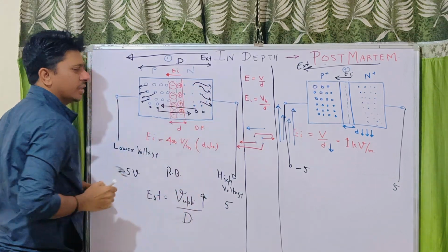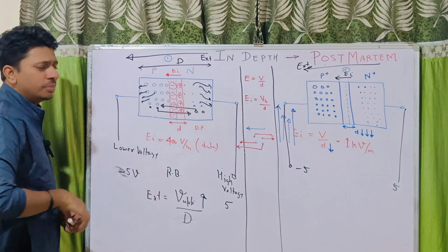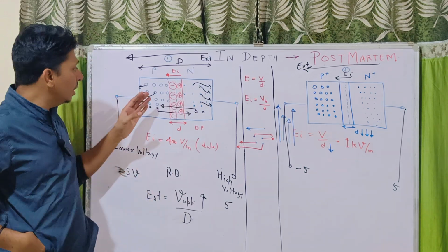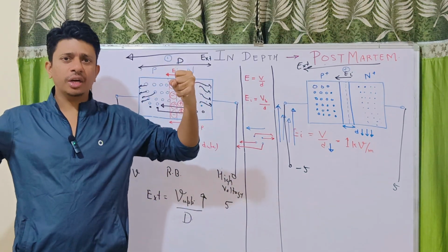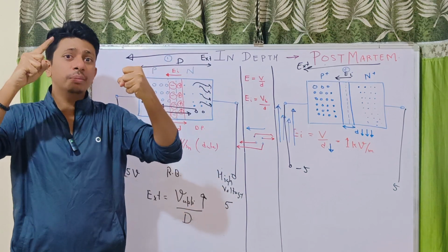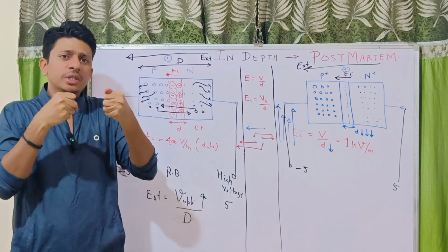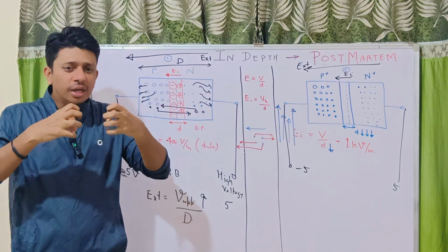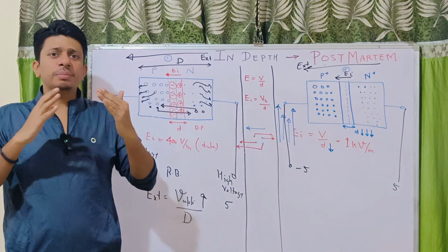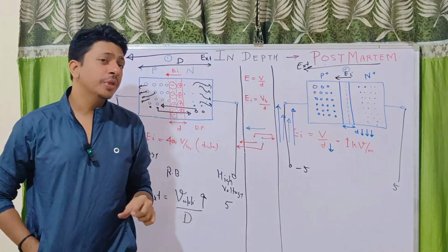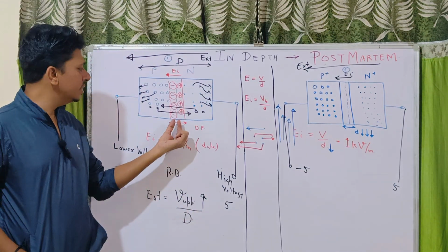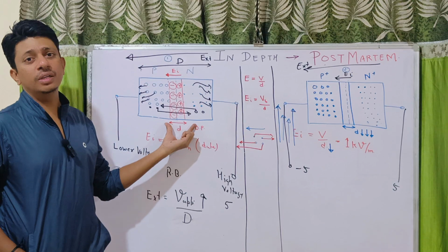attracted in this direction. As soon as you reverse bias this junction, earlier both the holes and electrons would try to move in this direction, and because of this these charged ions were getting squeezed. But now they are free, they will expand, and that is why people say that in the reverse bias condition the depletion width increases.